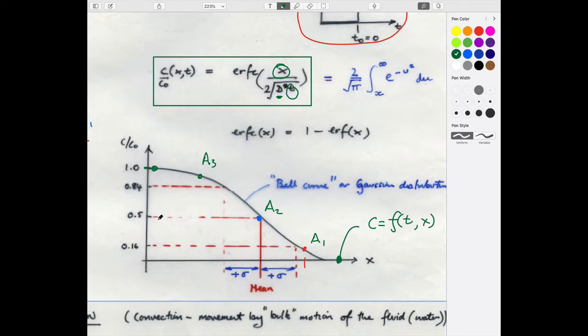So concentration as a function of location and time, given the diffusion coefficient in the aquifer. This is a snapshot for one time. So this curve is for time equal, I don't know, 10 days. It's not, but it could be, for one particular time. And if you looked at what that curve would look like in 20 days, then I suppose it would look something like this. And you can calculate it from here. All that would change would be the magnitude of this, and you just put a whole bunch of x's in there to do it. So, pretty straightforward.